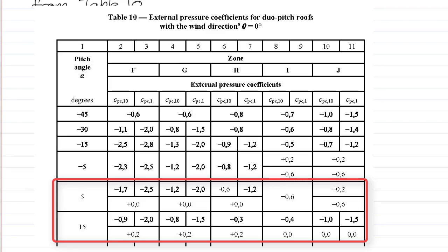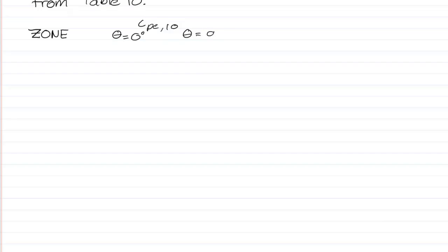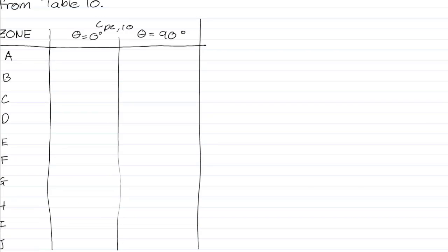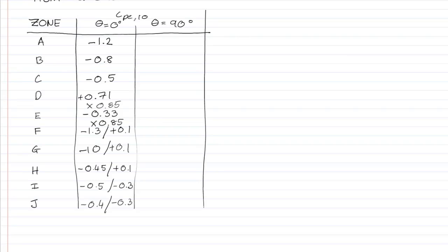Once we've done that for the two sections above, we can start filling in all the pressure coefficients. So I'm going to set up a table now with all the results in that you can then copy down and use. Here you can see the pressures for the side and the roof. Just to remember, we've put two diagrams together to get here.